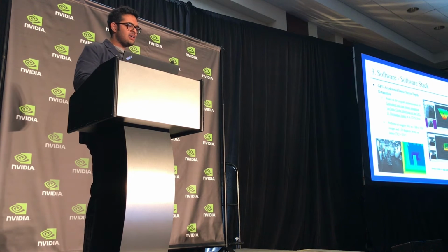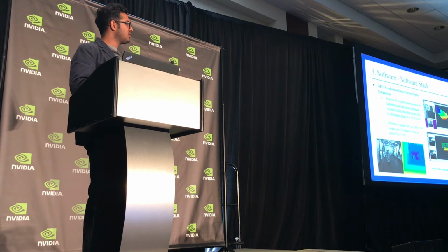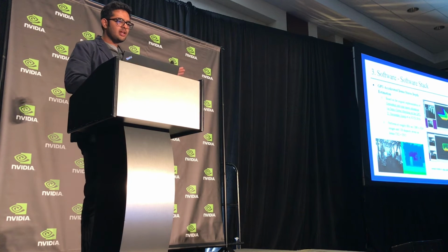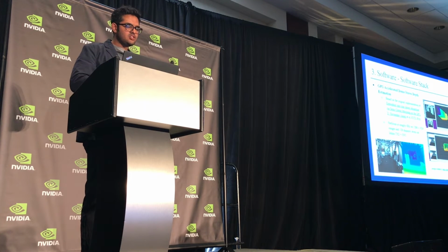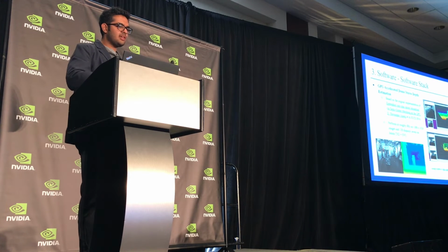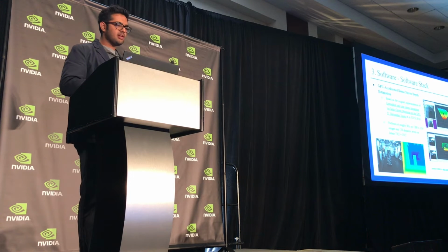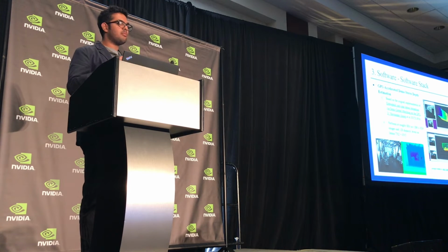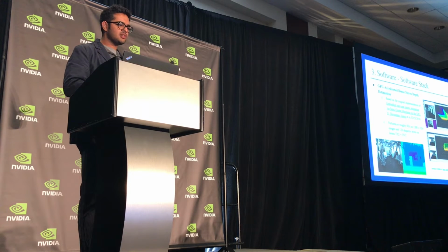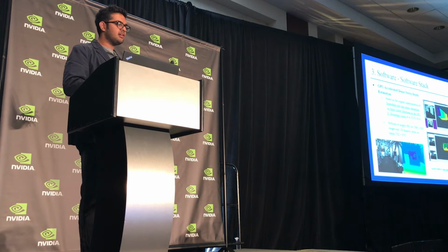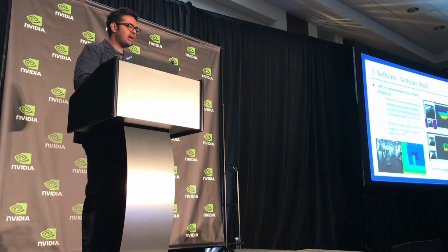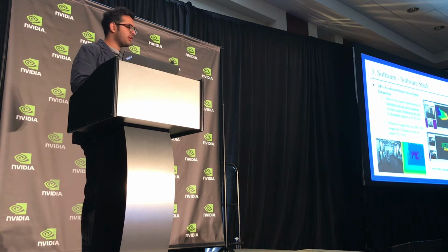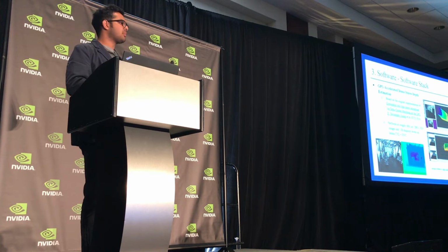This is some of the work that I did, looking at dense stereo depth estimation. It's a lot of GIFs, but I can walk you through it. So on the left of each is the grayscale image that we work with, and at the bottom is the corresponding right camera image, and the colorful point clouds are real-time results from the TX2. At this time, it wasn't the Open Vision computer. This was running on an Orbitty, the Connect Tech Orbitty carrier, and we can roughly do about 8 frames per second on a roughly 1.3 megapixel image at about 128 disparity levels.